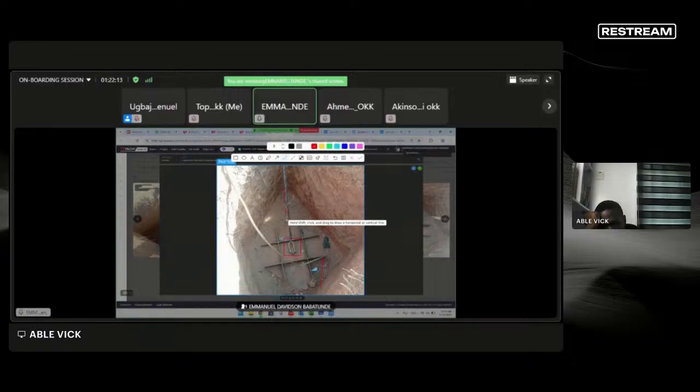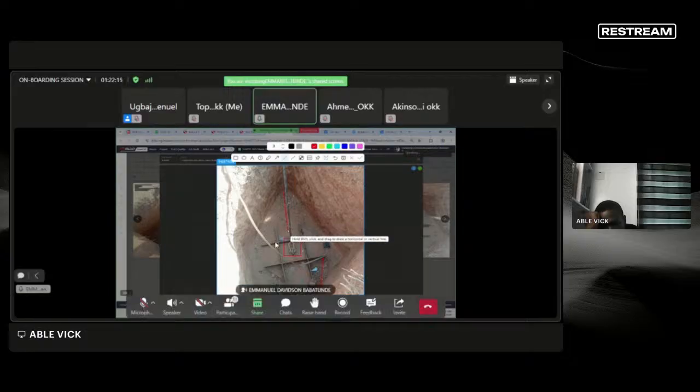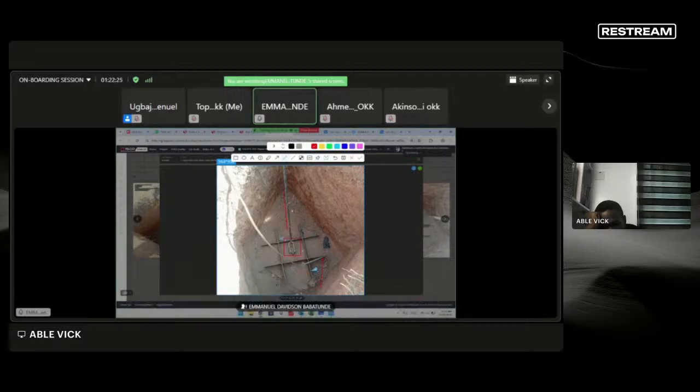You see this trench and this tip must align. So the base plate needed a small rotation to the right, so that the tip of the base plate is in line with the 5-meter line.